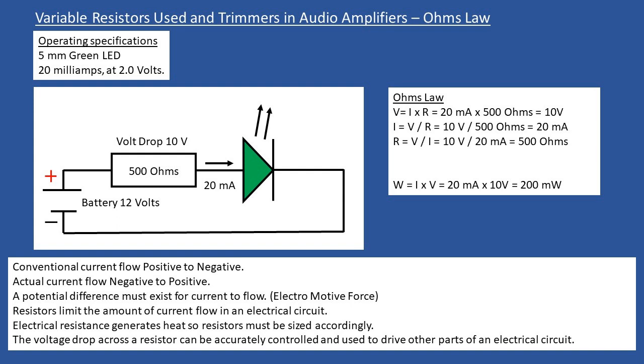Now whenever you get any form of electrical resistance within a circuit, even a piece of copper wire or maybe a gold plated contact has resistance. It might well be milliohms, very very small, but if you pass an electrical current through it, you will get a voltage drop.